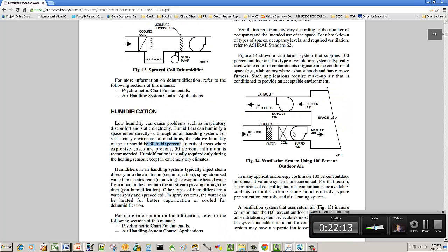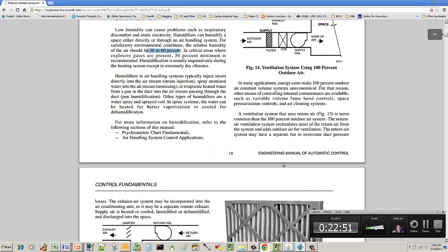So what's going to happen is you're going to have air come in, air goes out. You have a couple different ways of this working. You've got a volumetric match, so the same amount of air comes in, same amount of air goes out. You've got a volumetric offset, which means a larger amount of air comes in than goes out. That creates a positive pressure. If more air goes out than comes in, that creates a negative pressure. Some spaces you want to be negative, some spaces you want to be positive. For example, an infectious room. You don't want that to be positive. You don't want to be blowing that crap all over the place. You want a negative room so that it sucks stuff in. And then once again, in a clean room, you may want that to be positive.